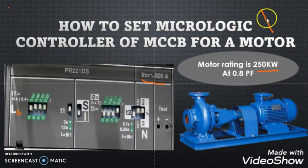If we select a breaker which cannot be adjusted, suppose it is a fixed 600 ampere breaker, then if any load increases or decreases, we need to change the breaker itself. But with this adjustment, we can adjust our breaker as per our load. And as you know well, the load is very dynamic. So this is the advantage of selecting a breaker which has an adjustment to change its nominal current rating.